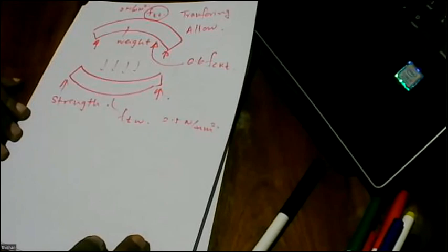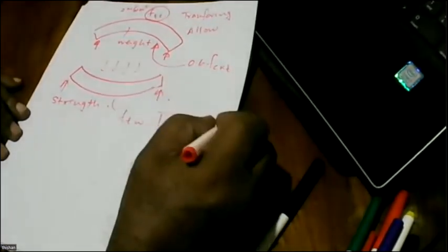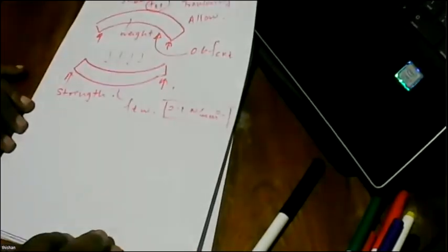In Eurocode, it doesn't say you have to stop at 2.5. If you want, you can go for higher stresses and get a more efficient design. But if you think durability is a great concern and you don't like any cracking, then you can maintain the tension around 2.5 newtons per millimeter squared. So that is all your decision.